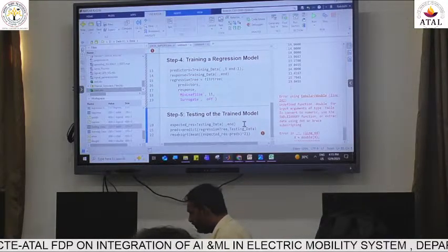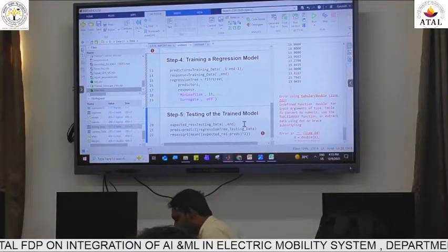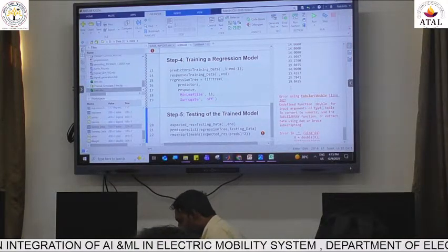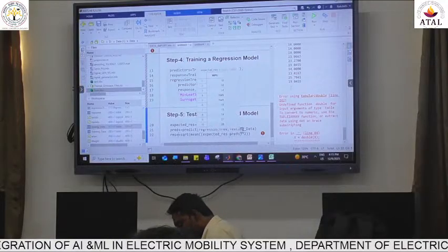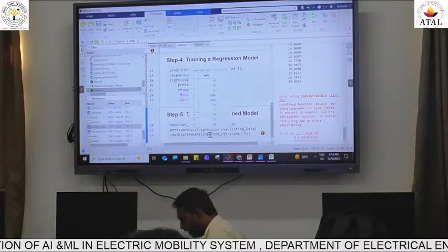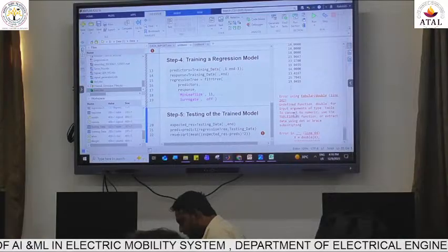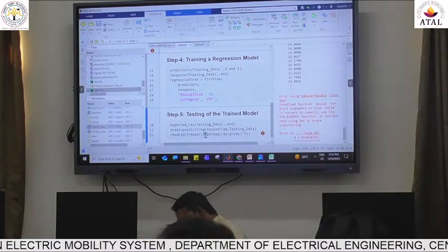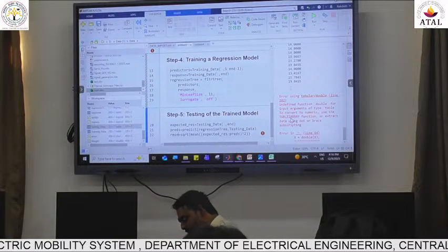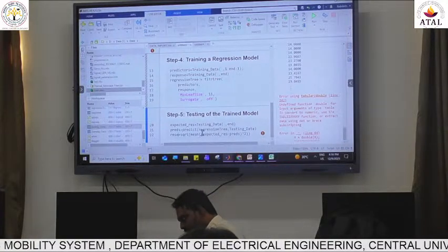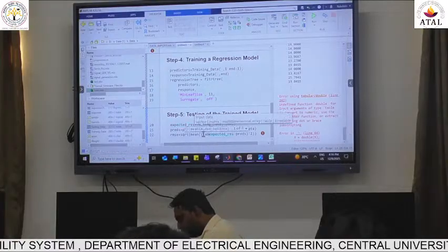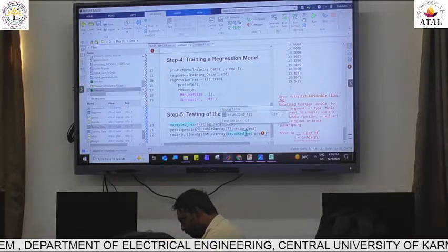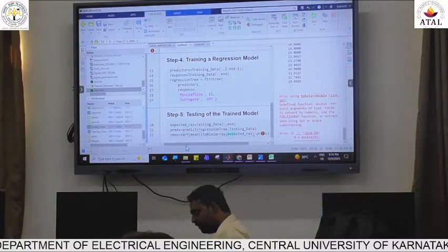Okay, I am doing some syntax. Sometimes this error can come. Let us see the error message and we can try to debug. We are taking table data here, the expected result, and it is telling us to convert that to a matrix. So this is table data, and for this you can use an inbuilt function to reduce the error. Let us use table to array, and we'll put it across this table. And now let's calculate.